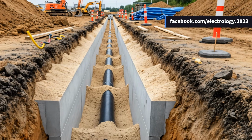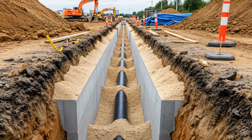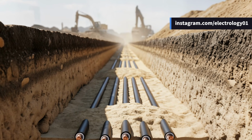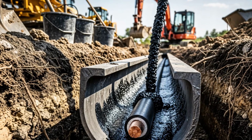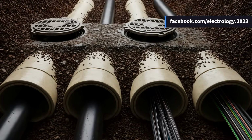When the heat produced inside the cable equals the heat dissipated to the surroundings, the temperature stabilizes. But when the heat cannot escape fast enough, the cable temperature rises and its permissible current must be limited. To properly calculate how much current an underground cable can carry, we must consider the thermal resistivity of the insulation, the protective coverings, and the soil.